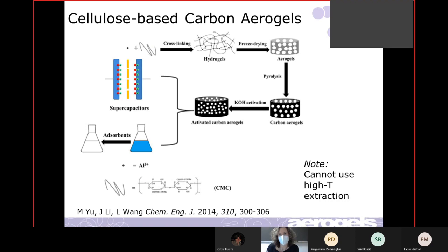The process here is a little bit different in that it's not necessarily a full sol-gel process, but you are still making a wet gel. Right? Depending on the size of these polymers, you could consider the solution to be a colloid. You could consider it to be a soluble solution. There can be a little debate there. This was a freeze drying application. They were not so concerned about monolithicity, and so freeze dried to yield aerogels.